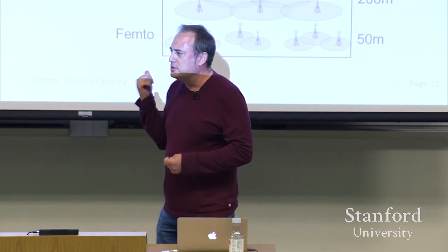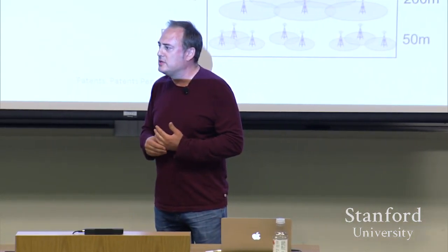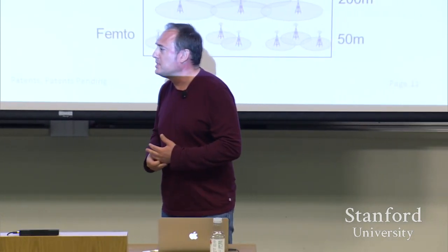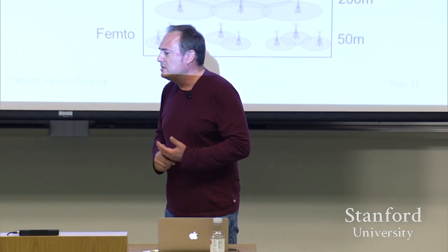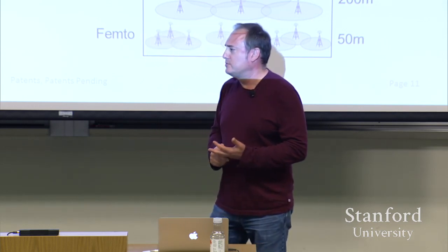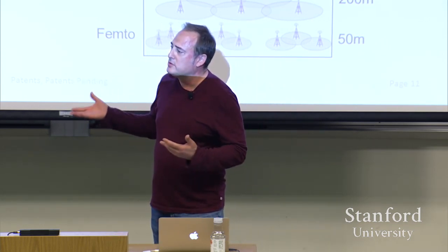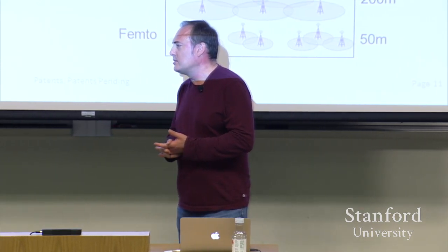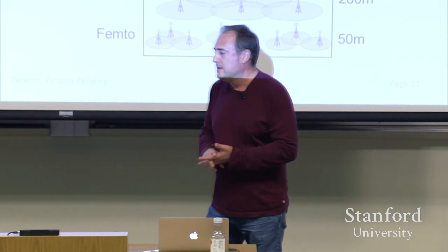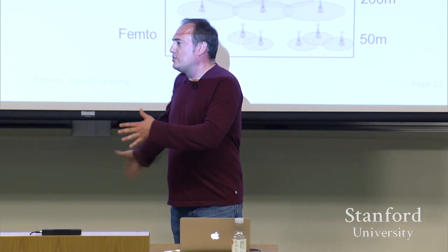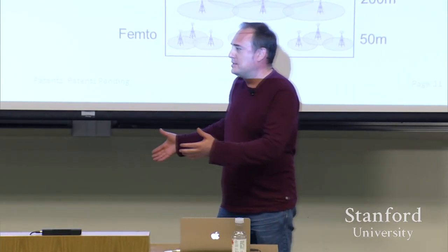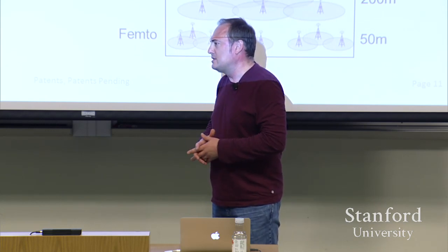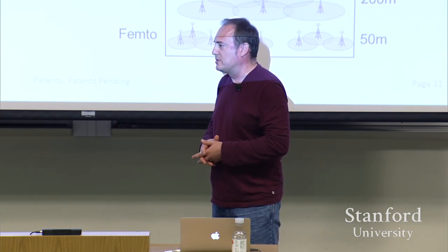Is that related to small cells, or just about the capacity? Oh, well, I mean, it's nowhere near 27 times. Practical spectrum being used today is, let's say, rough numbers, between 500 megahertz and 2.5 gigahertz. So that's about 2 gigahertz of spectrum, right? Well, let's say that everything all the way down to HF was vacated. That'd be 500 megahertz, right? So I think we're pretty much out of spectrum.